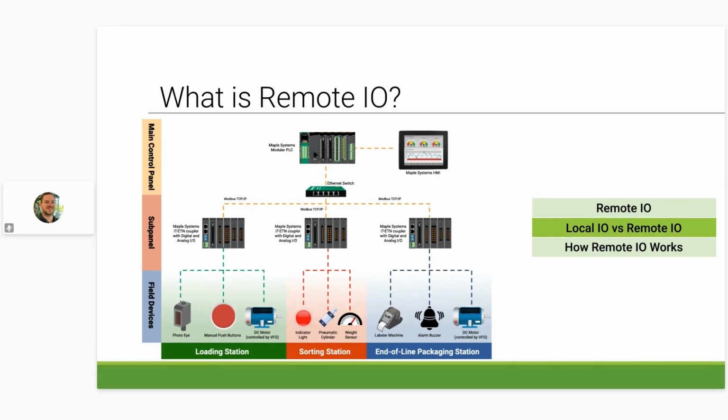Local I/O refers to devices that share a direct connection to the main controller or field devices within a short distance that are generally within the same control cabinet or close by. There are several characteristics that we look at when evaluating both local and remote I/O. Some of the key considerations include proximity, wiring, latency, reliability, maintenance, and cost.